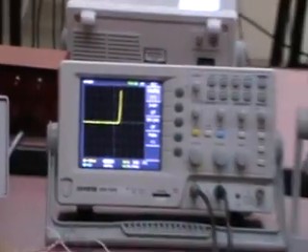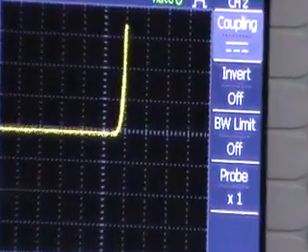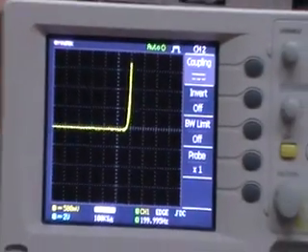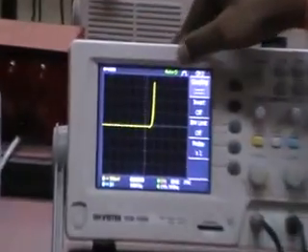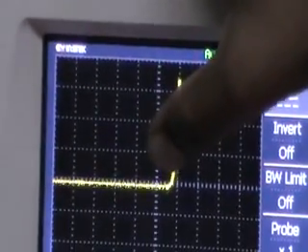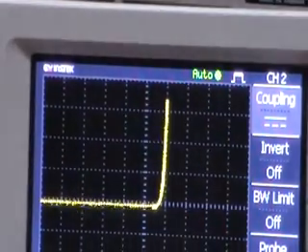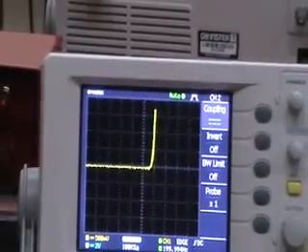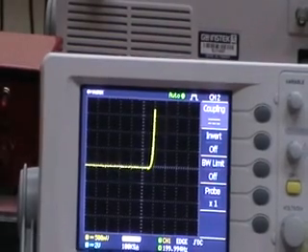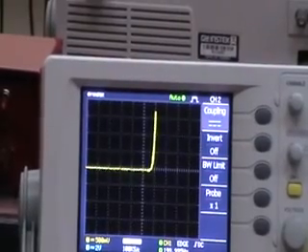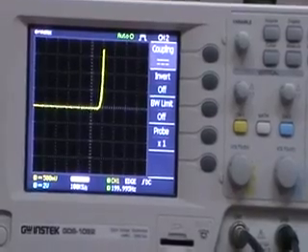So we can verify that we are getting the correct diode characteristics. Next, we have to estimate the knee voltage V gamma of the diode. By observing the waveform here, we can observe the V gamma by using this voltage per division across channel 1. We can easily get the knee voltage. For this part, we should keep the channel 2 voltage setting at 0.5 volts per division or 0.2 volts per division. By that we can easily observe the knee voltage.